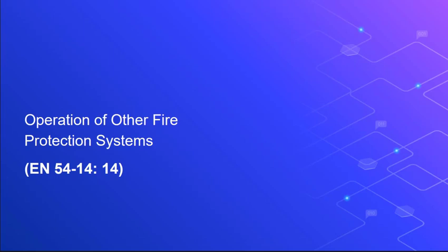Article 82. The emergency control system that will automatically perform the necessary control functions in case of fire. A. Releasing the electromagnetic door holders and similar devices that keep the devices for closing fire doors and other openings that need to be closed during a fire. B. Activation of stairwell and elevator shaft pressurization devices.